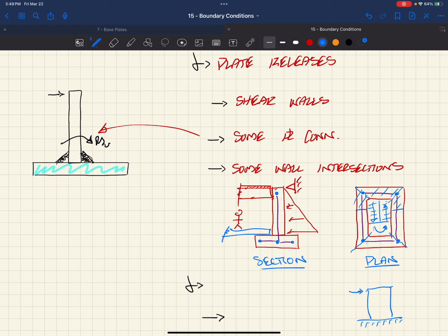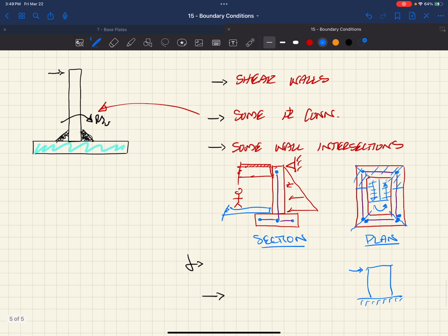I've mentioned to you, sometimes what I've done is I've just doubled up nodes at these corners and actually just created independent plate walls that are extending up, but then are just gapped by a little bit. Again, there's a lot of different ways to do it, but these are some areas where you'd have to think about, well, how are the forces going to transfer? Or how do I want the forces to transfer across these intersections of elements?